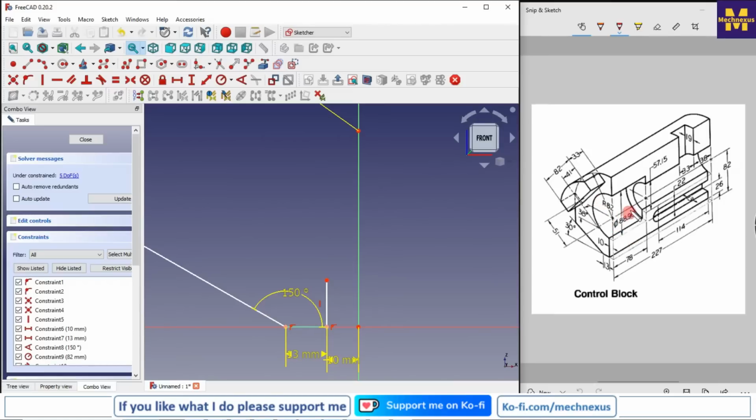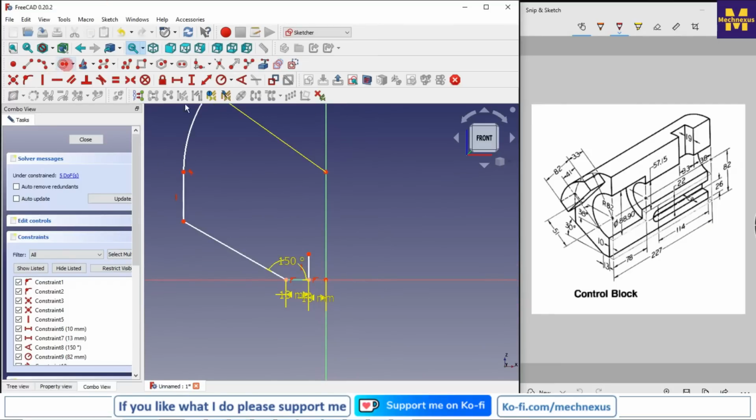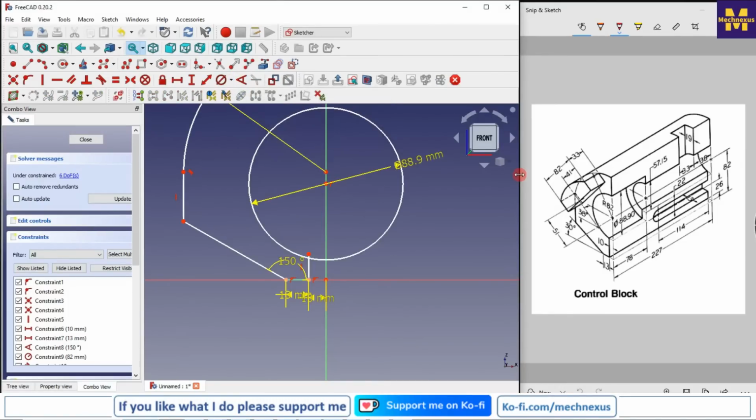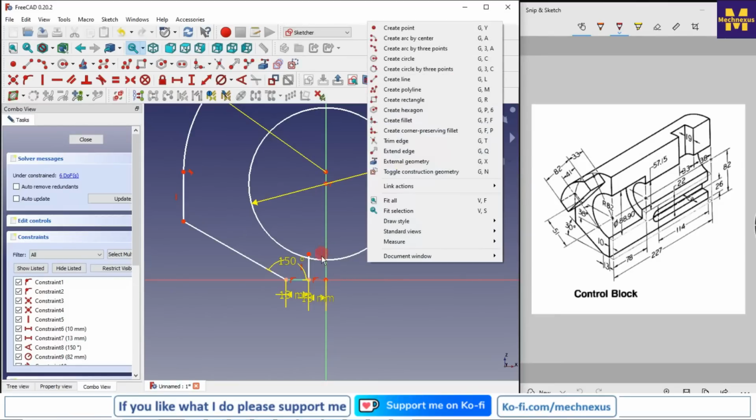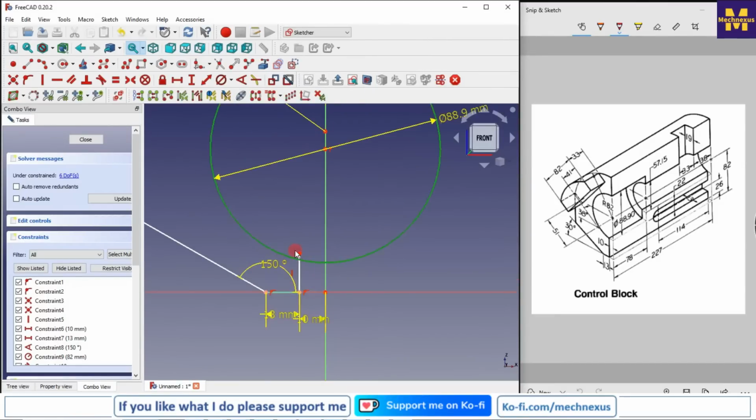and this bore is diameter 88.9. So I will draw the circle and give it a diameter of 88.9, and then I will select this diameter and this point and give the constraint,